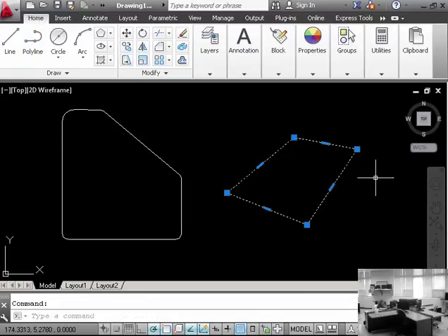Another great little tool is, for example, the polyline command, as you note, that it's one continuous line. The explode button allows you to click on objects, hit enter, and it becomes multiple lines after the fact. So, just get through some stuff.